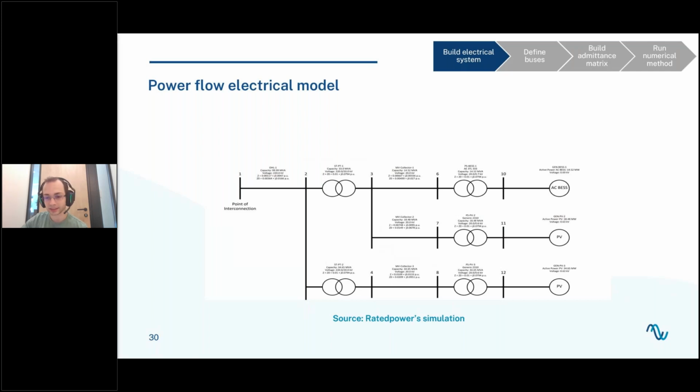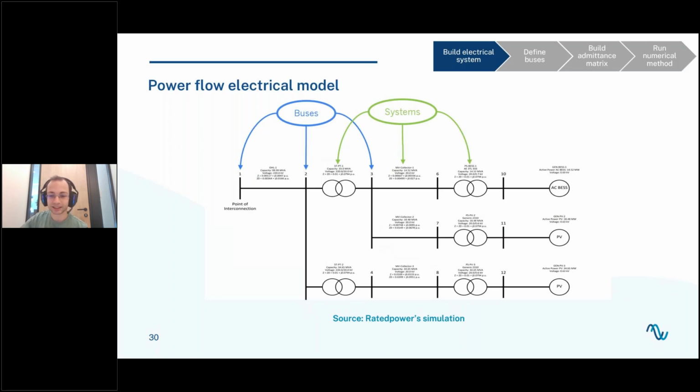And given this tree, let's say this graph describing all the elements, all the electrical systems, you can then move them into a different software such as DIgSILENT or PSS/E to run your power flow analysis. So here you have the systems and the buses numbered to make it a bit easier. And this is all following the WECC guidelines.